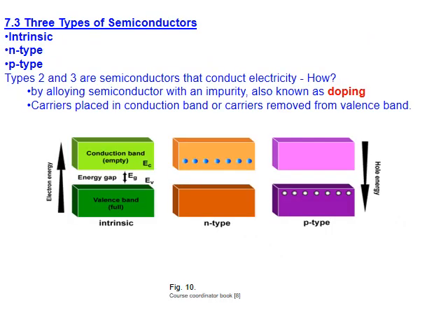Okay, now what happens with this semiconductor? We come to this semiconductor. This is the intrinsic, the pure, let me say, semiconductor. We try to use doping, putting in impurities. As an example, for each million silicon atoms, we put in one atom of some other material. This will create either n-type, negative type, or p-type, positive type.